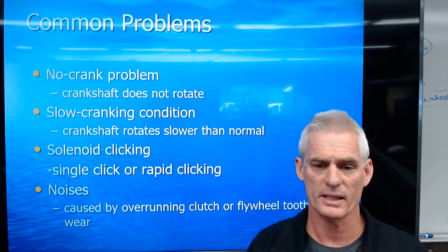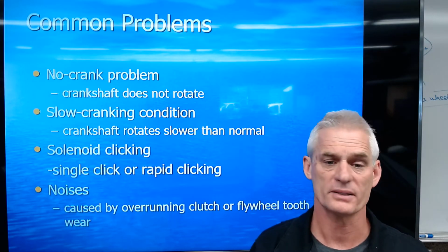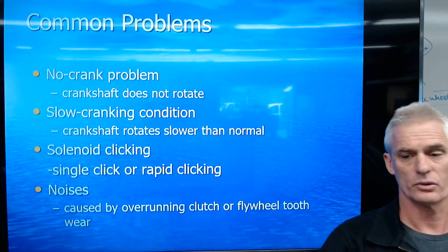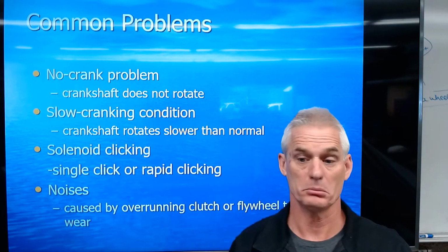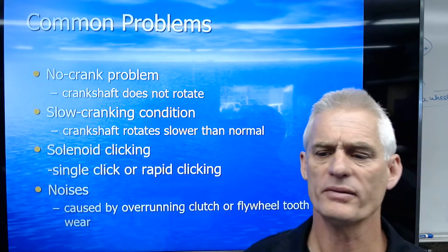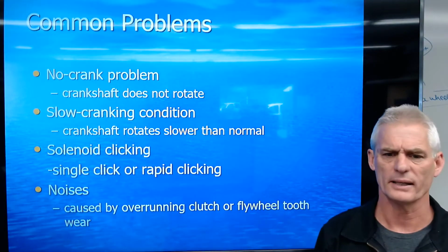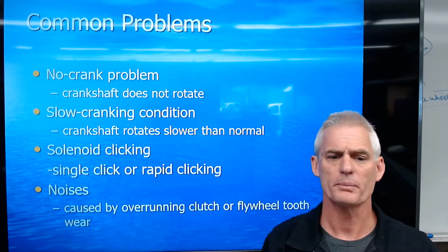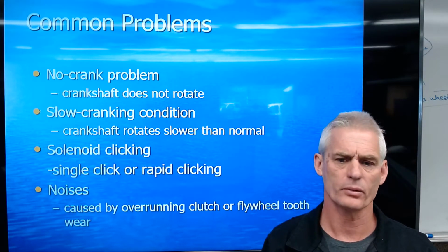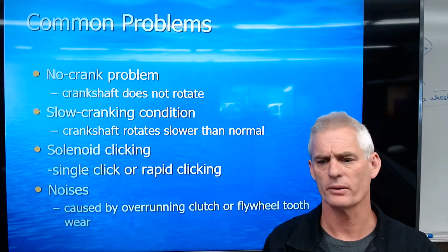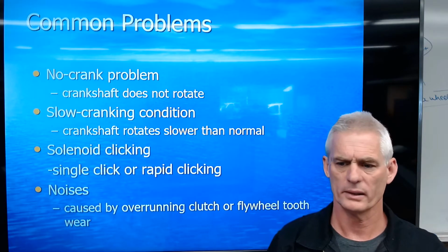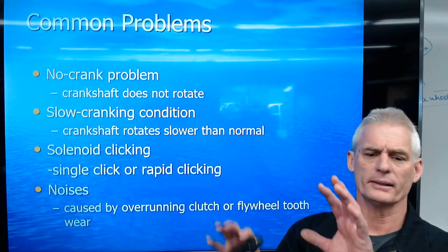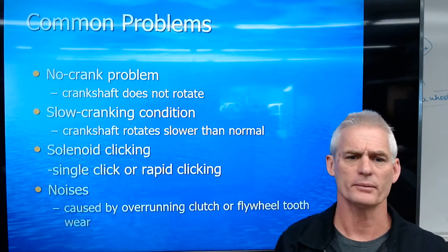And it's important to identify what's happening because if the cranking speed is normal, it's spinning and it's not starting the engine, well, we obviously don't have a battery problem, or most likely we don't. We've got some other kind of problem. So people are quick to replace batteries. People are quick to replace starters when they're not really sure what the issue is. So hopefully this helps at least a little bit in separating the different conditions that can be.